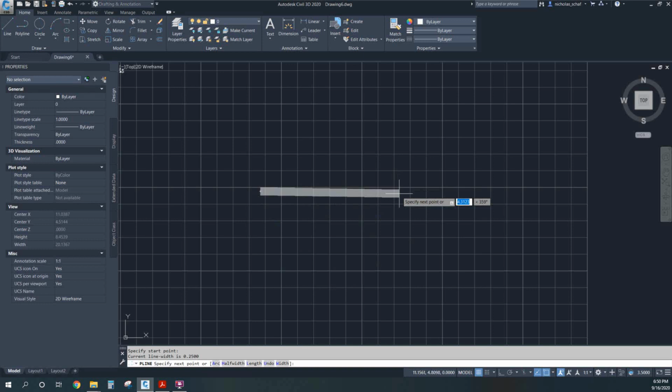Going back to polyline, anytime you type in a width of the polyline and then you end the command, it will always keep that until you type in width again and specify it to be 0. So in this case, I am going to draw 2 lines here, and let's say that these 2 lines here are a pipe. This is, let's say, a water pipe.